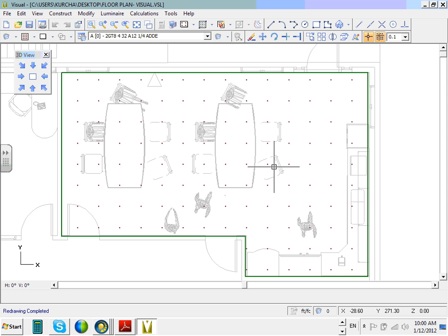Can you guys see? Typically, they leave 2 feet off the wall and they place the first fixture. So that gives you a hint how to place your fixtures and how far away from each other. Typically for these, this will be a good example here. Here's 1, 2, 3, and you put the third one. From edge to edge, can you see how they leave one space here? Unfortunately, the grid did not show up here, so we're going to do it the old man way.